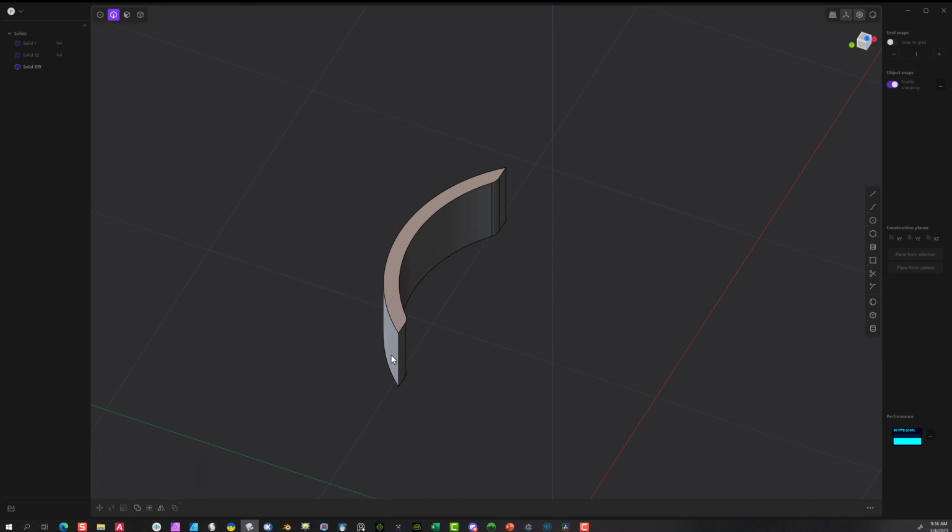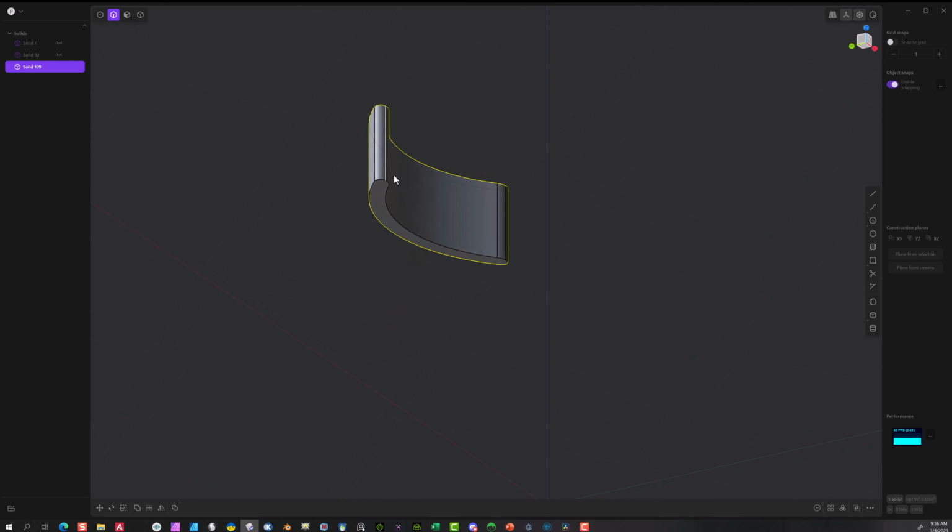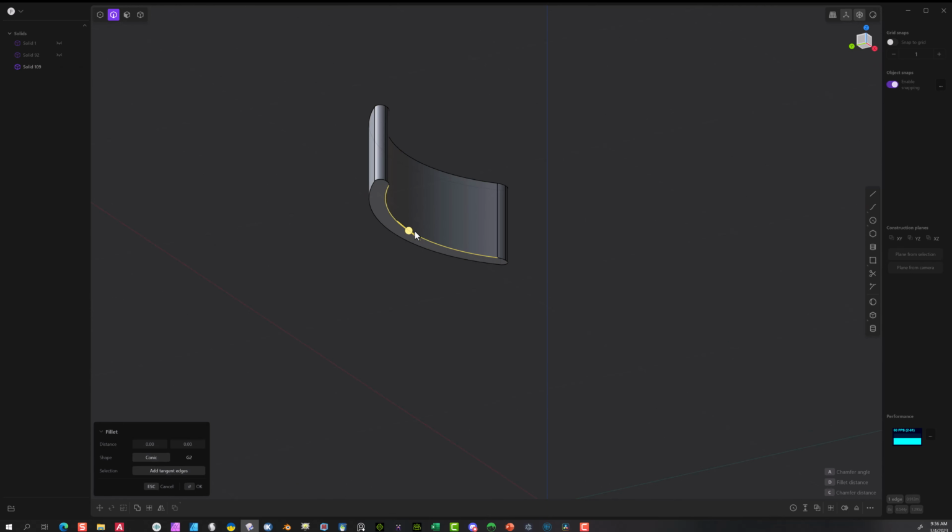Say OK. Same thing here. I'll try to do the last one at this side back first and then the front one so I can see what I'm doing. And then see it's more of a rounded edge right there. Okay, I went with 0.2285. Say OK. Another thing you can do is, now everything's rounded, you could actually select one of these edges and again do a fillet and it makes it round. If you had an edge sharp, it won't do it properly. Say OK. Alright, so that's that.